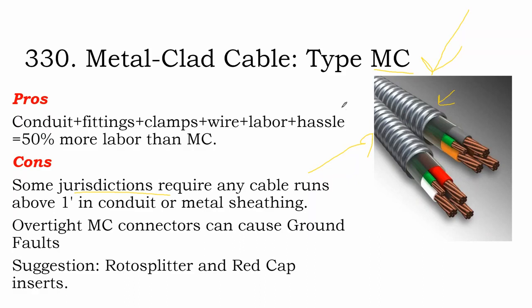But I think for solar, having this metal is, hey, none of the other power lines in your house are in metal, and the utility feeder entrance conductors inside your house don't even need to be in metal, and they're at a much higher power capacity. I think that this metal protection is really for critters, so that they don't chew up your power lines, and I think that can make sense. This is one area where the United States has a more expensive solar industry than in other countries, but you get what you pay for.